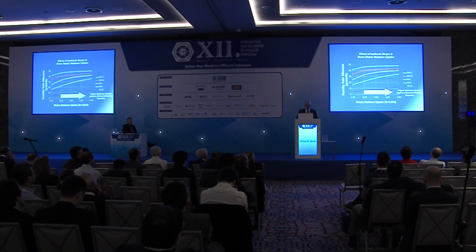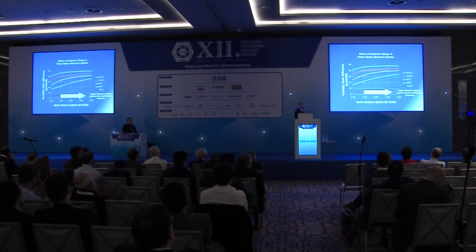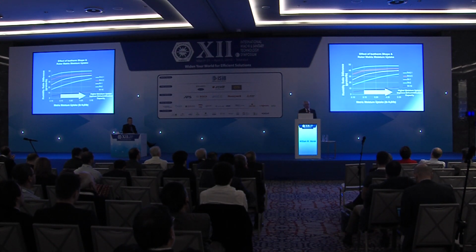If we look at the effective isotherm shape, that's what I was saying before, you'll see the linear isotherm, this is our silica gel in yellow, has a given value, but if you want deep drying, that's why you always go to the stronger adsorbent. So in other words, deeper drying, stronger adsorbent, or higher temperature, stronger adsorbent.